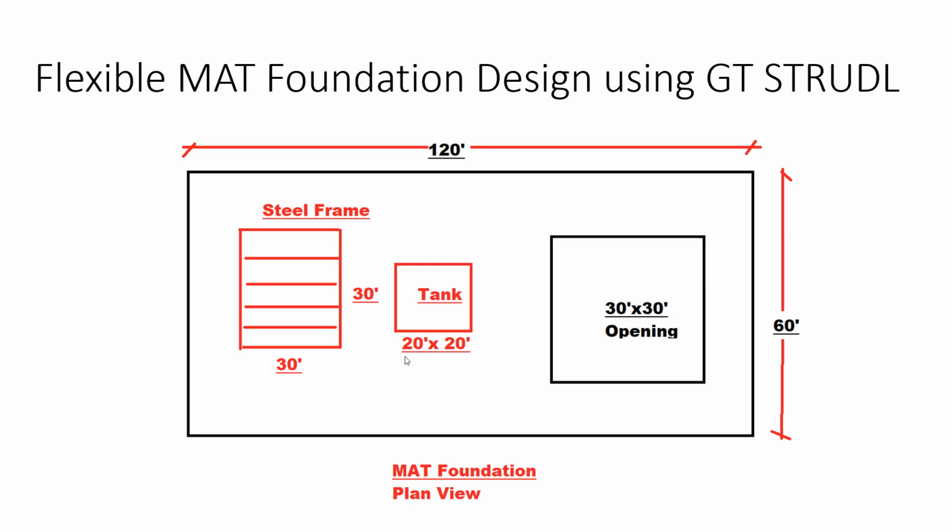The reason why we use quadrilateral plate elements is because it's easier to interpret the results, because the local coordinate axis system of the finite element meshes are going in one direction.